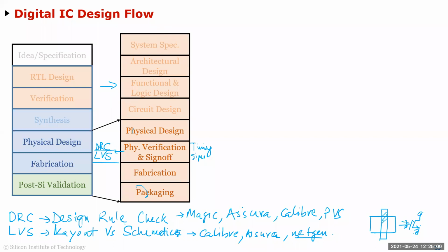Yeah, so in the physical design verification and sign-off, some extra steps are taken. One of the main ones is timing sign-off, in the sense that the timings are done using tools. There are a lot of timing verification tools which are used, like the open source tool OpenSTA. So after the design is synthesized, the tool uses all the synthesis data, post-layout and post-P&R and post-synthesis data, because now it has all the parasitic information and all that. So the timings are all going to be worse now than what they were before.